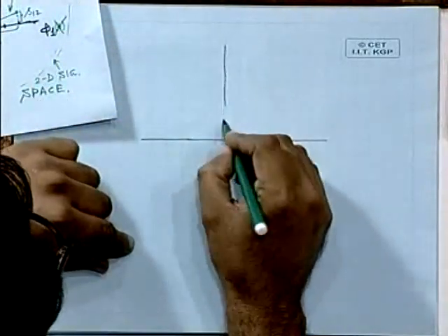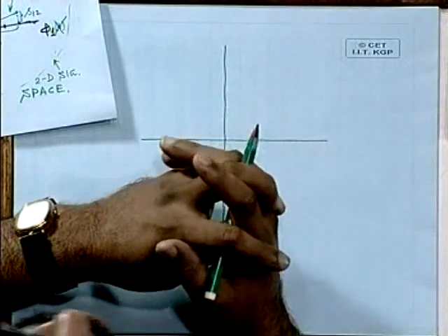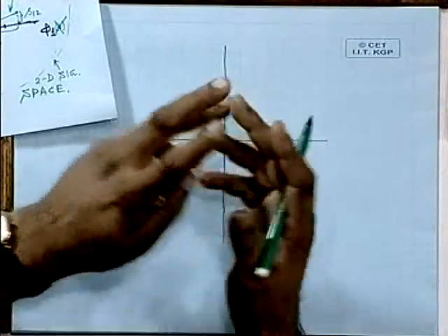Yeah, the point is that all this discussion is valid for a narrow band transmission scheme, which means that after carrier modulation, the signal that I will get will have narrow band, and hence I shall be able to equivalently represent it by its corresponding low pass representation, isn't it? And this low pass signal we know is a baseband signal. Now, if I tell you that these are my low pass equivalent signals, and this is my carrier frequency, I tell you the same thing. When I say that this is my carrier modulated waveform, these are equivalent descriptions, is it not?